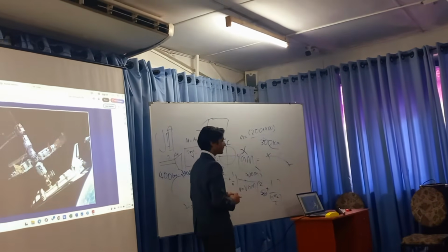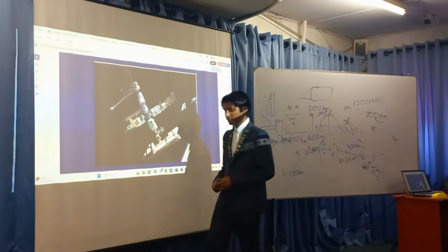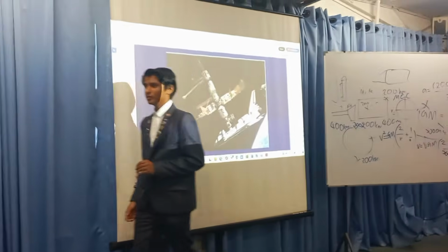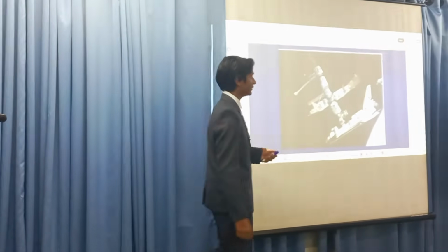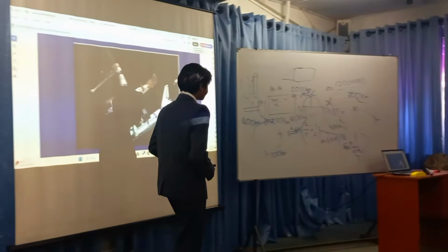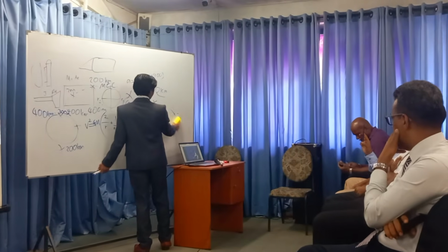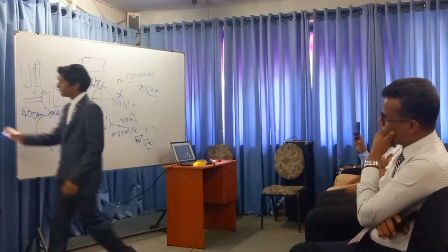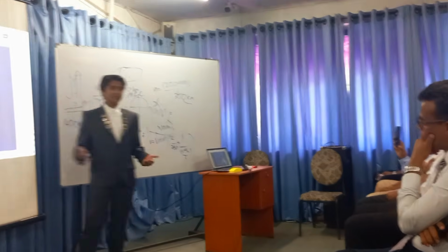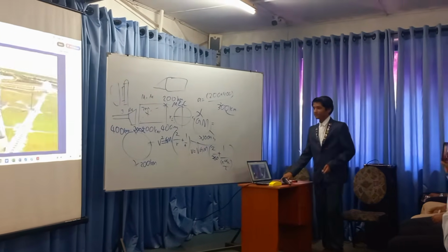Once we have completed this, the space shuttle and the space station will be only a matter of kilometers away, and at this point, mission control, as well as the astronauts currently inhabiting the ISS, will help to guide the two craft together. This happens through a process known as docking, and at this point, thrusters like the OMS will be completely irrelevant. The OMS thrusters, which you can see here, will be of no use, and we need to use a system called the RCS thrusters.